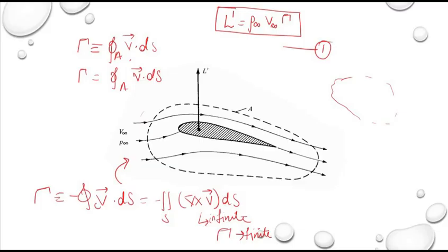So in theoretical analysis to calculate lift, in the case of two-dimensional bodies with incompressible inviscid flow, what is usually done is to focus on calculating the circulation of the body. Once you obtain the circulation, you obtain the lift per unit span using the Kutta-Joukowski theorem. So this was all about the Kutta-Joukowski theorem. Thank you for listening. Stay tuned.